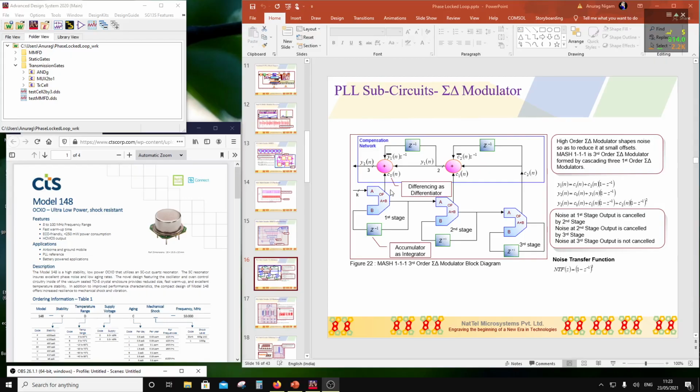So that's why I'm not doing 16. I'm going to do a 12-bit Sigma Delta modulator, right? So these accumulators are going to be 12 bits. So let's do a 1-bit accumulator, and then from there we go on to do a 12-bit.